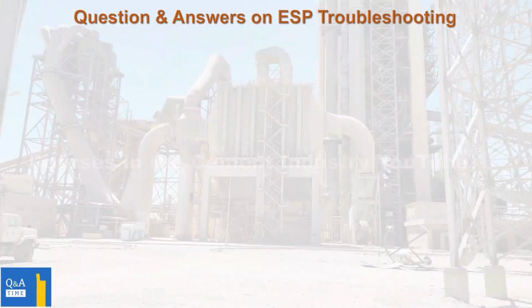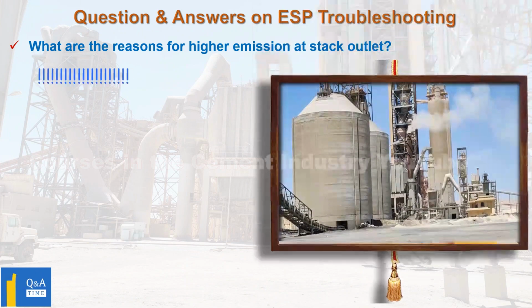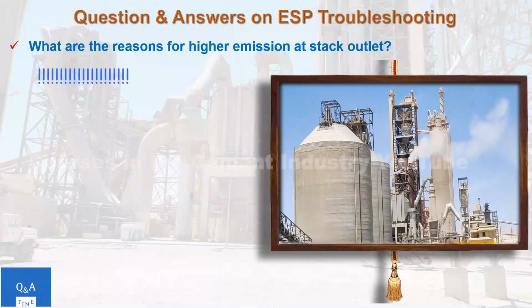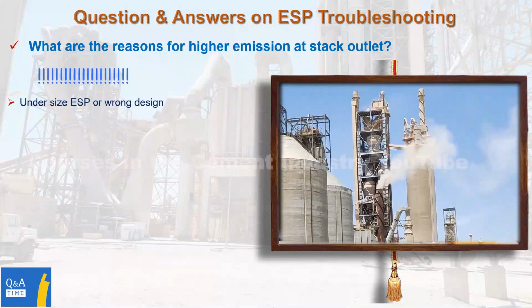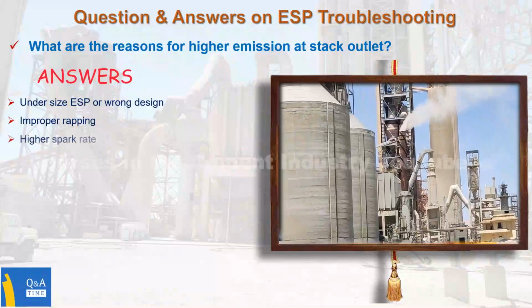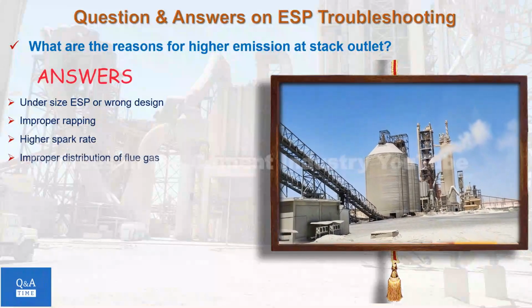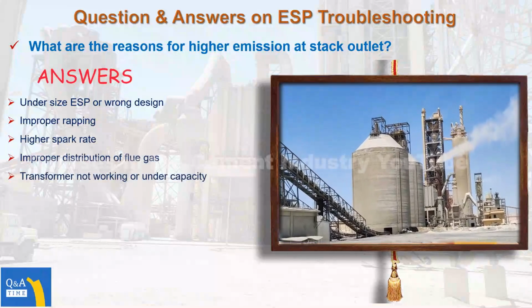Question 3. What are the reasons for higher emission at stack outlet? Answer. 1. Undersize electrostatic precipitator, or wrong design. 2. Improper wrapping. 3. Higher spark rate. 4. Improper distribution of flue gas. 5. Transformer not working, or under capacity.